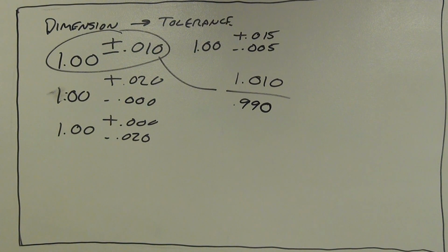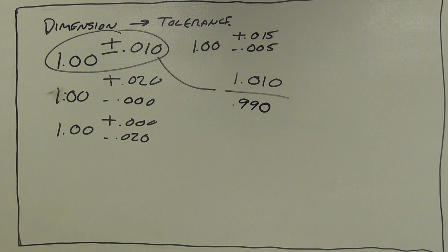Now, is that useful? Yes, it is, because if you're making parts, it's very clear to you that if you make a part that has a feature that's supposed to be 1 inch 10 thousandths, if it's 1 inch 11 thousandths, you've got a problem. You have to remove some material, or if it's a hole, you can't do anything, you have to scrap the part. So anyway, it's a very explicit expression of what numbers are important in terms of making that part and meeting the requirements of the design.